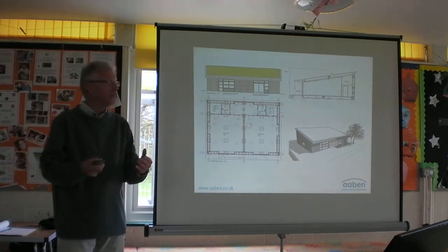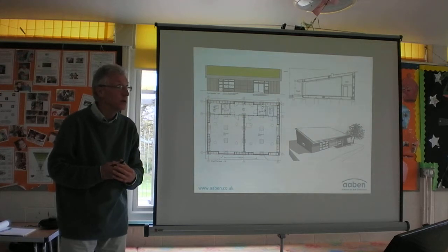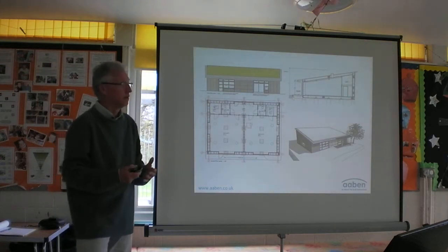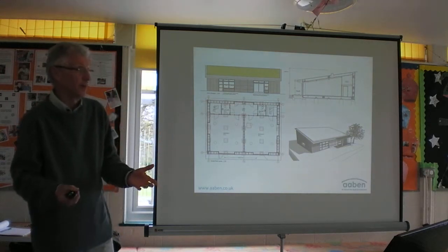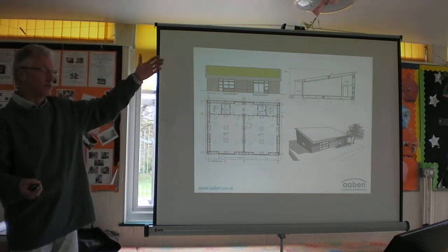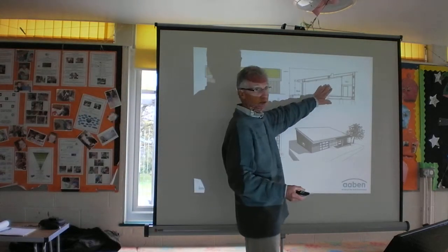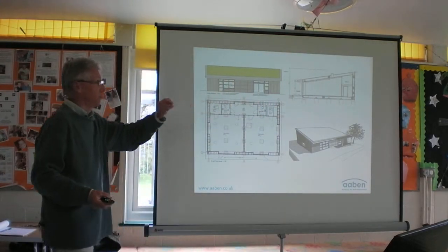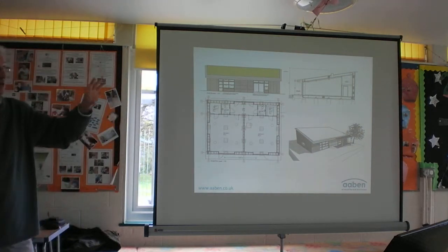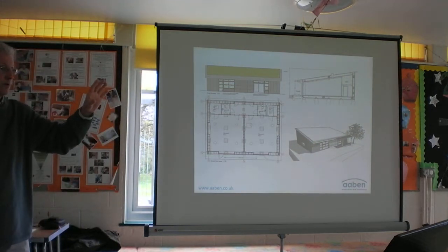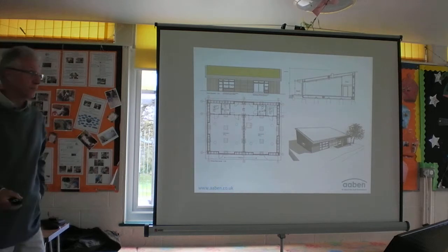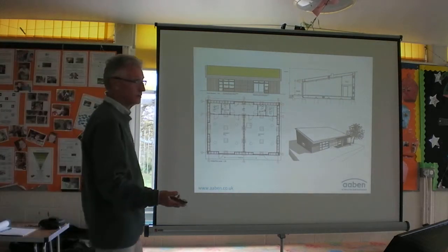Would I be right in thinking that is controlled then? So some electronics control. You can either have it manual, or you could have humidistats or thermostats. So if this building, let's say, hit 24 degrees during the afternoon with all the kids in it, you can have a thermostat which controls that ventilation, clicks it open at, say, 6 o'clock, until the building drops. Just like the conservatory, yes. Same system.